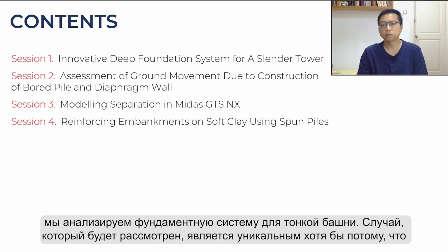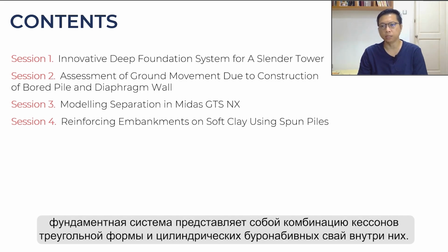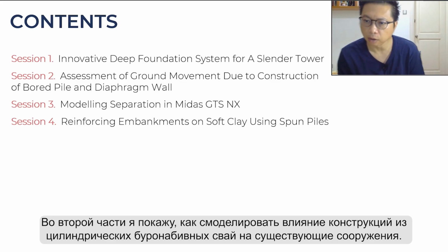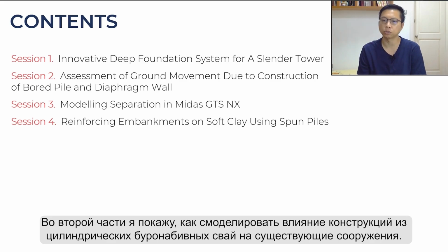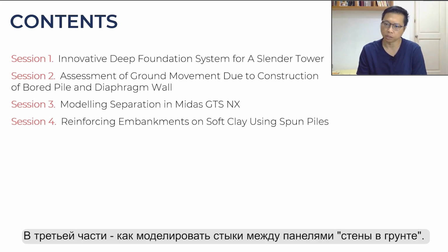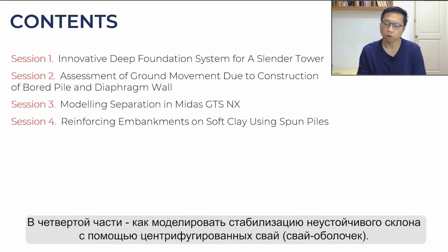This is unique simply because the foundation system is a combination of triangle-shaped coffer and a few bored piles within the coffer. Number 2, I will show you how to simulate the effect of construction of bored piles on the existing structures. In session 3, I will show you how to model separation in between different wall panels. Number 4, I will show you how to simulate stabilizing a failed slope using spun piles.